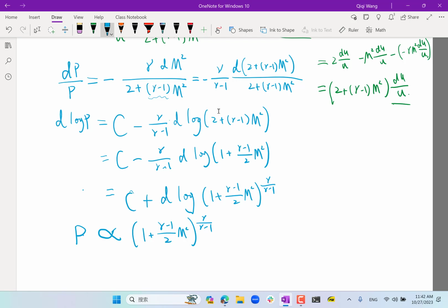A multiplicative constant outside of the log becomes a power of minus 1 inside the log, so this is actually minus. So if this thing is equal to 2, then after the minus sign, this is equal to half. That means as you decelerate the velocity to 0, the right hand side is going to change from half all the way to 1. That means the pressure is going to rise by a factor of 2.